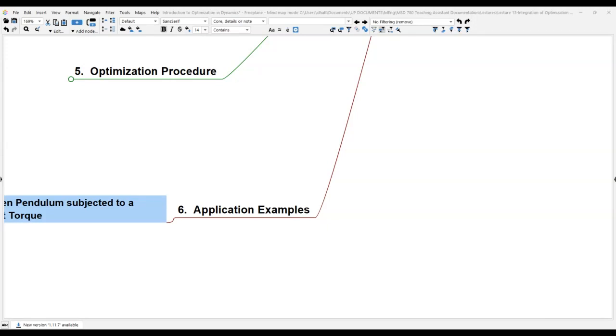Then you want to include your initial design parameters or initial variable choices, and also your optimum design. Once your optimization is completed, rerun the dynamic analyzer with those optimum design variables and see what the new graphs and results are. And it would also be nice to see the optimization histories, like we saw now.